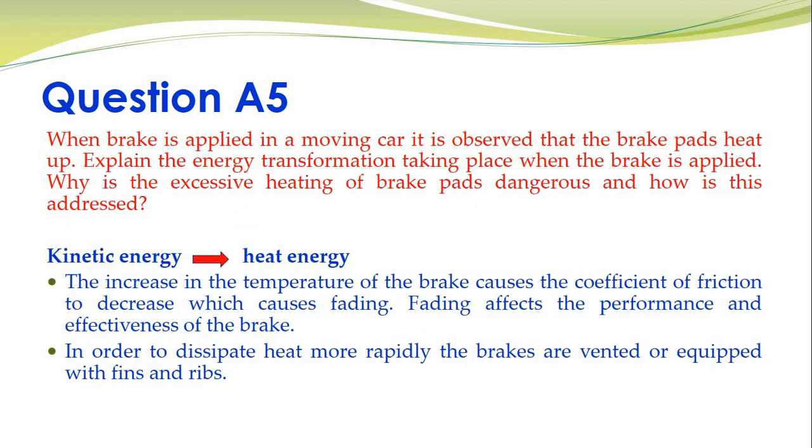Moving on, it says that when a brake is applied in a moving car, it is observed that the brake pads heat up. Explain the energy transformation taking place when the brake is applied, why the excessive heating of brake pads is dangerous, and how this is addressed. So the first thing is, you need to look at the energy transformation. A moving car will have kinetic energy, and once you apply the brake, the kinetic energy is converted to heat energy, and this heat appears as an increase in temperature of the brake pad. So that's your energy transformation taking place.